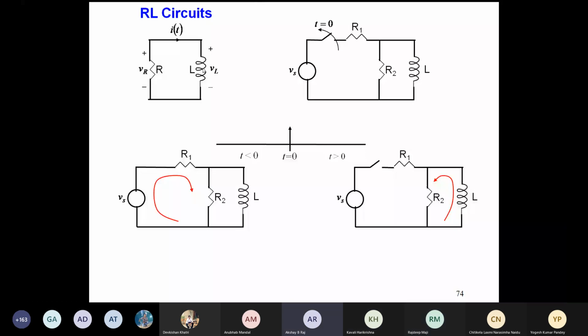If R2 is replaced by a zero resistance, then will energy be dissipated? Then the inductor will not charge. Then the inductor will be short circuited by the zero resistance. No, but you have to give the inductor some other element through which it will dissipate.